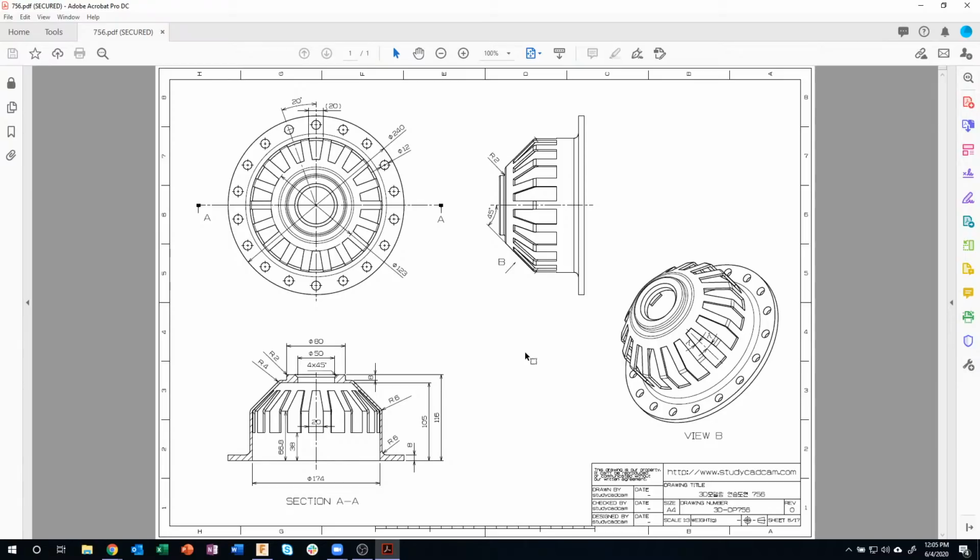And I looked at this one and I said, okay, how would I approach this? It's not overly complicated. We're going to probably do a side profile and revolve it. This is my guess. And then I'm probably going to have to create these little air vents or whatever they're called. But you'll notice that they're slightly tapered. In fact, it's kind of hard to see right here. It looks like they're at a 7-degree taper. So I'm going to have to figure out how we're going to go about doing that. And then obviously I would probably pattern them. Let the software do the hard work here.